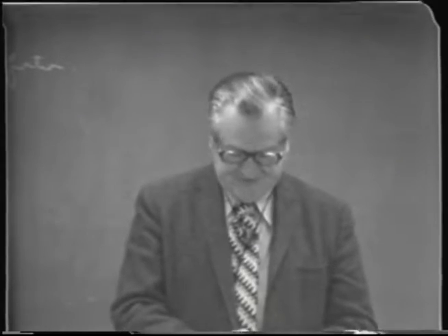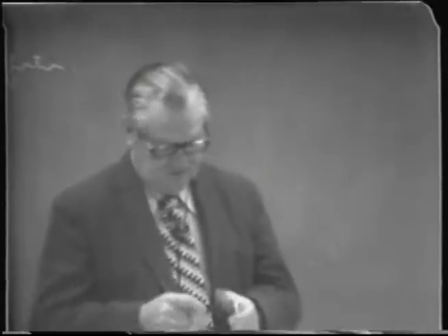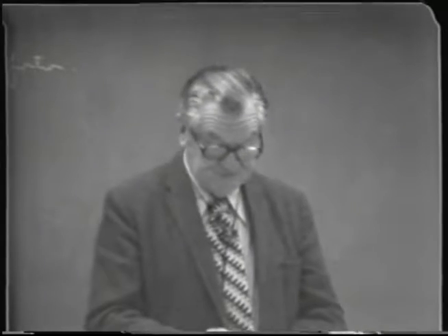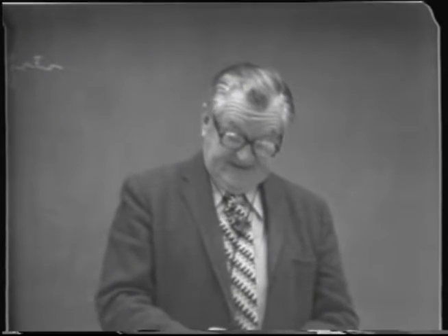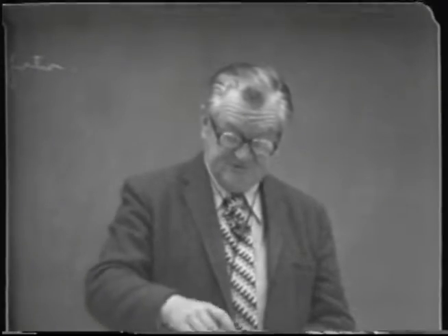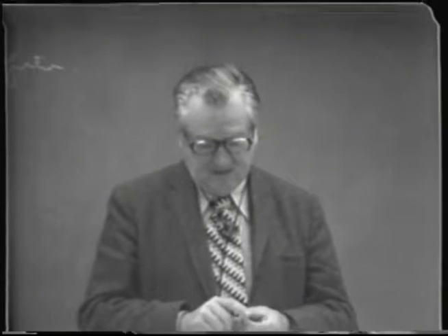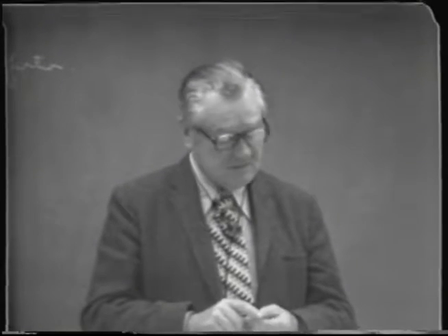And then this region of essentially straight line across here represents the region of the heterogeneous azeotrope till you get up to around roughly 50% isobutyl alcohol. And then the curve goes up, but it's below the diagonal line, so that means that above about 33% isobutyl alcohol, the volatility of isobutyl alcohol is less than water.